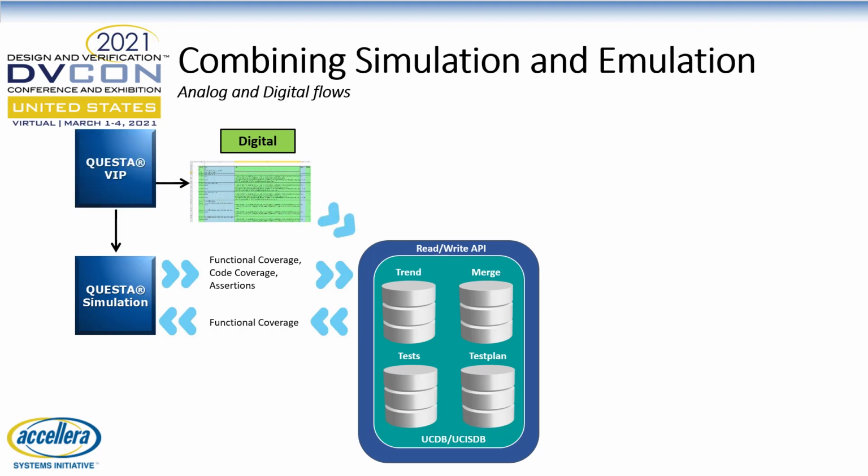When you include Questa verification IP in your simulation, you automatically augment your test plan to include all of the aspects of your specific protocol, but also all of the covergroups, coverpoints, and crosses needed to ensure that you've fully verified the interfaces.